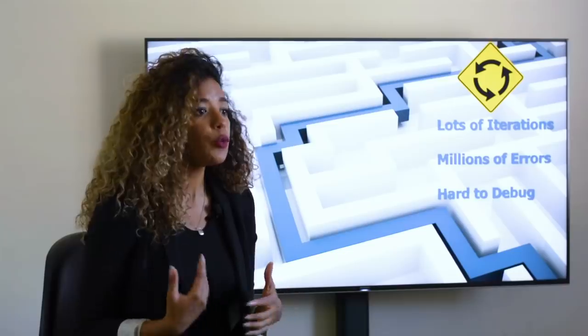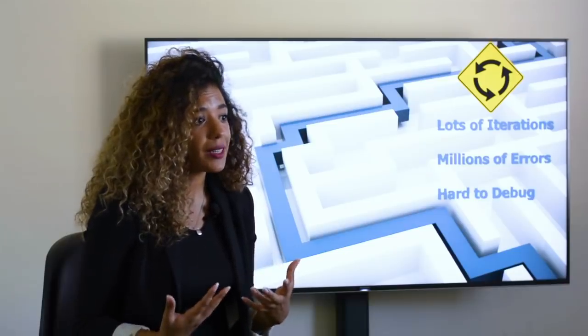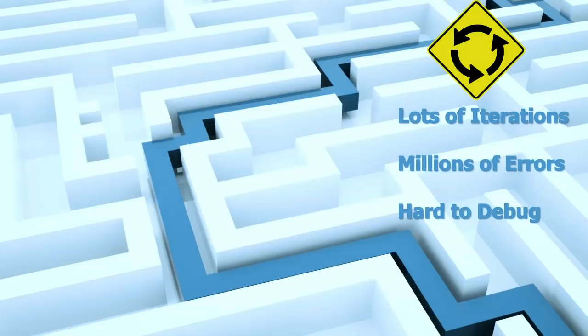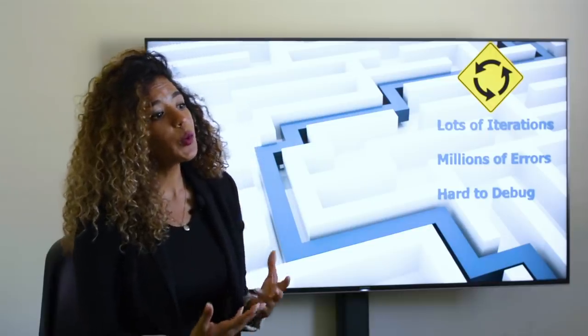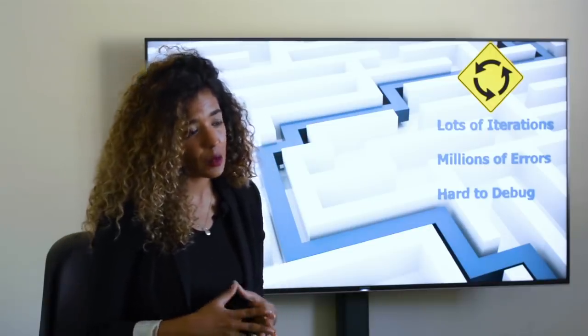Designers will tackle this problem by prioritizing the errors, fixing the most important ones, and iterating through the design cycle. Running sign-off LVS on dirty designs is often an overkill, as all the circuit errors cannot be addressed, therefore all the checks should not be applied. This is the paradigm where we launched Calibre DRC-Recon at DAC 2019. With DRC-Recon, we have improved the efficiency and designer productivity for physical verification. We're now offering a similar use model for circuit verification.